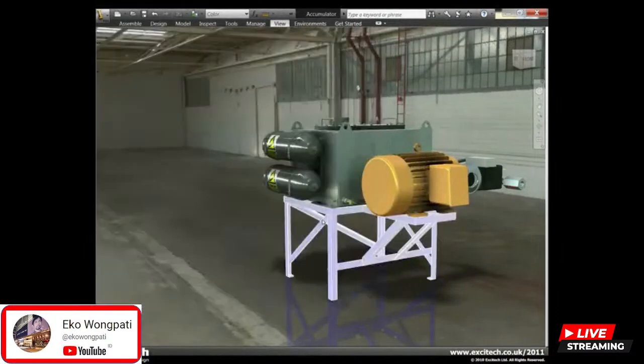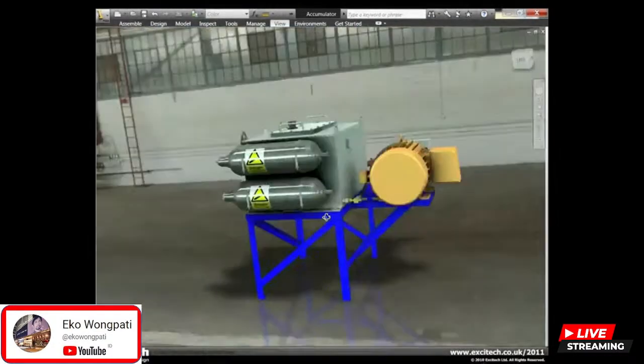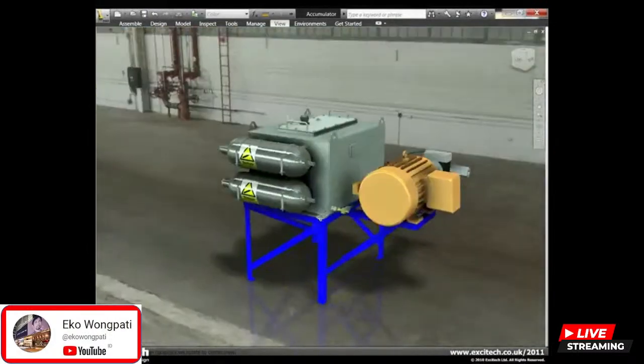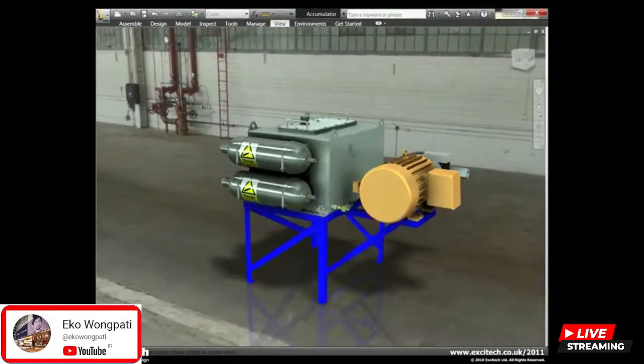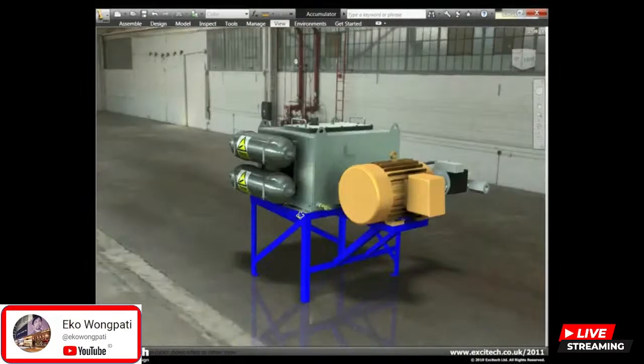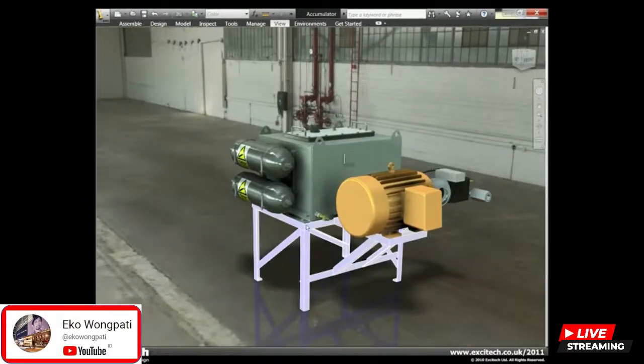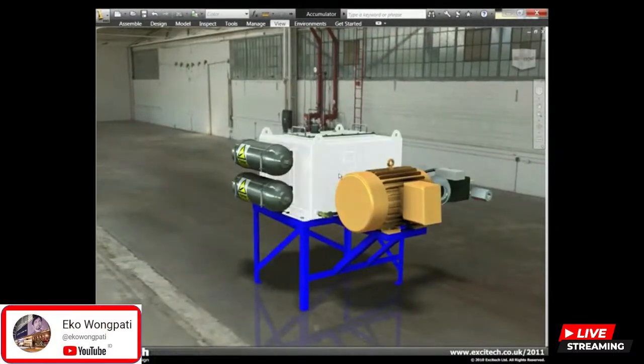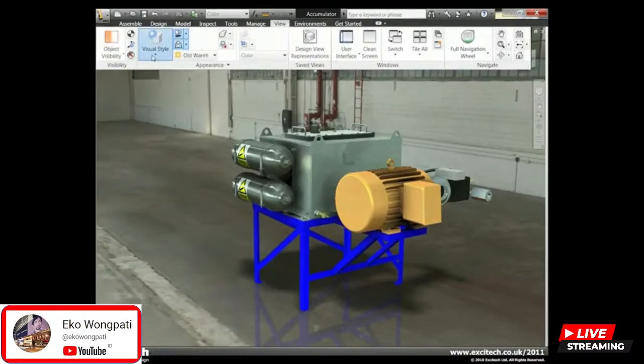Now, at the moment, we are still just using the Inventor shading environment. What we can do is make use of this expanded materials library. As we've just said, Inventor now shares its high quality visual materials library with products such as Showcase and 3D Studio Max. So let's now switch on realistic mode.